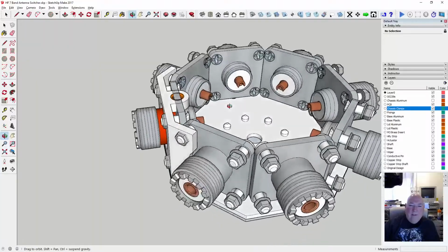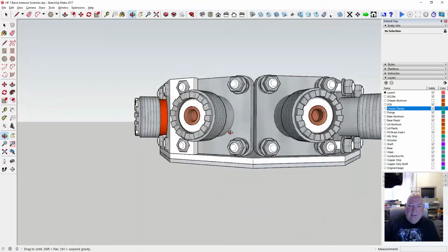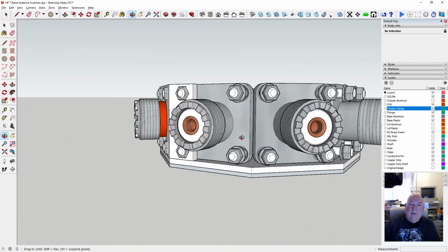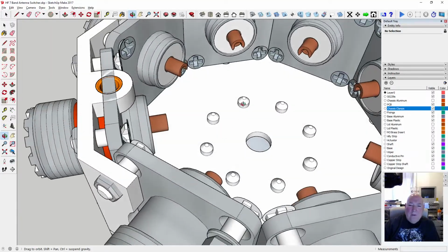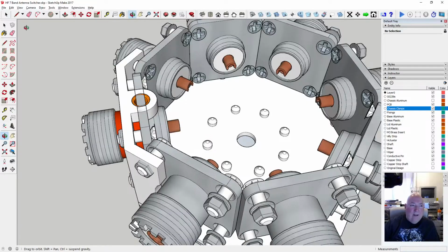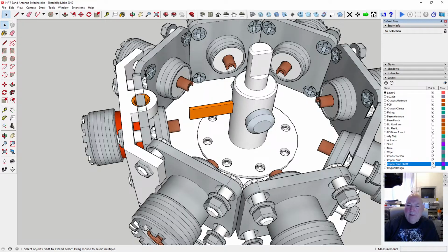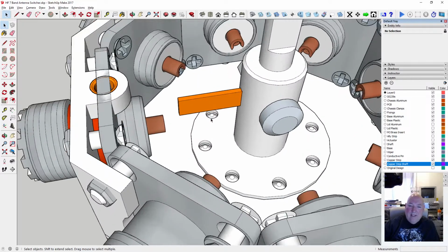We want to put the plastic on the outside and the aluminium on the inside. So what we're going to have to do is mill out the holes. Instead of having the holes in this piece, we're going to have the holes in the aluminium.